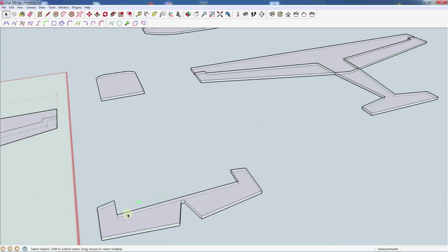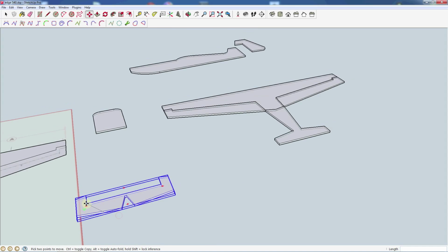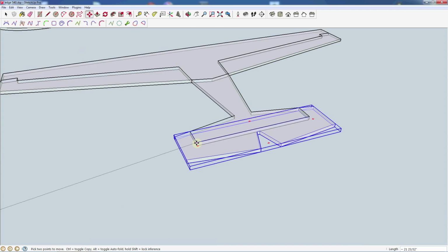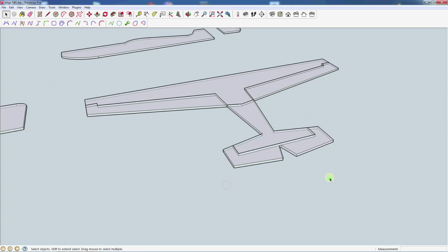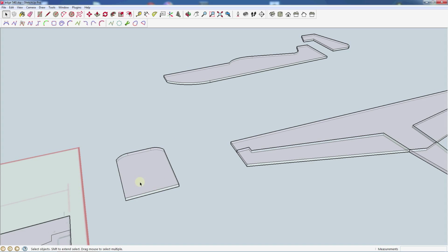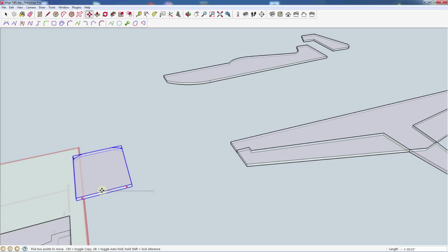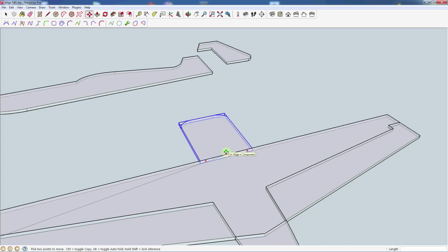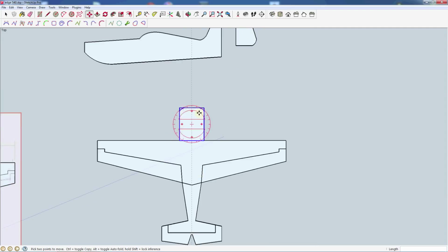And let's get our elevator. That's in place. And this one, since we don't have a good reference point there, we do have our midpoints. So I'm going to grab that and make sure I grab it by the midpoint and component there, and bring it over here till it says, should be able to get it to snap to the midpoint. There we go, midpoint. Now if we look at it from the top, it should look all straight and aligned.